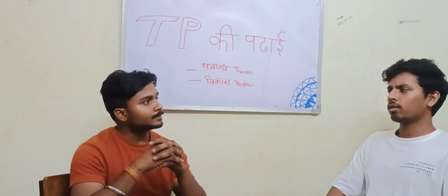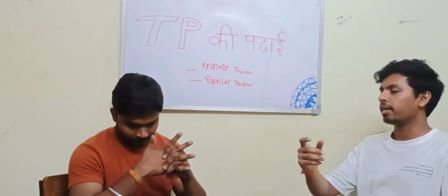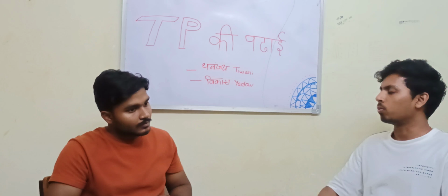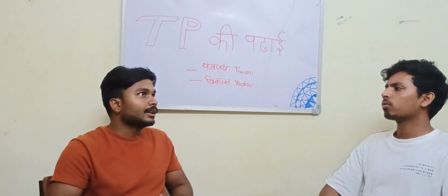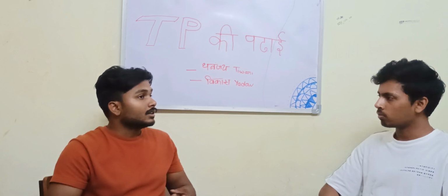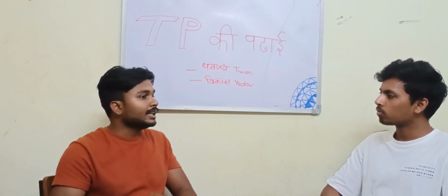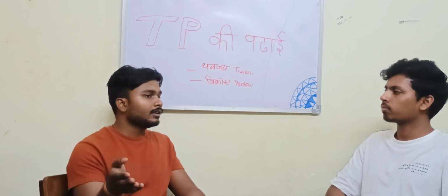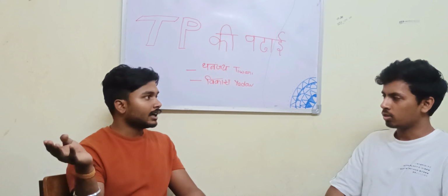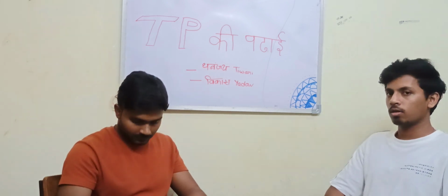But many times the temperature difference is not given, the temperature difference is not constant, it is varying, and the area is not given. So in that case, what can we do? We studied in transport phenomena that there are various empirical relations like Prandtl number, Schmidt number, and some analogies like the Chilton-Colburn analogy. From those dimensionless numbers, we can easily calculate the required parameters like h, k, Cp and everything. So use the values of these numbers, get the coefficient and put it in the formula, and you can easily get the heat transfer coefficient. Okay, so this is a very important thing to note down for our students and viewers.